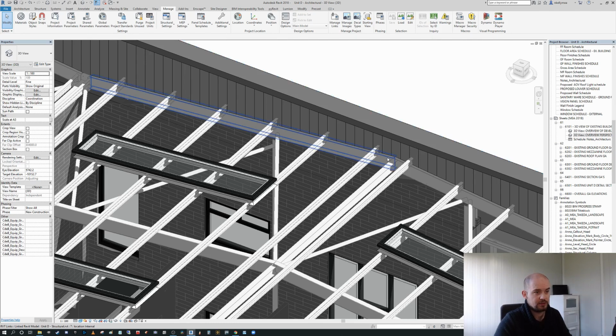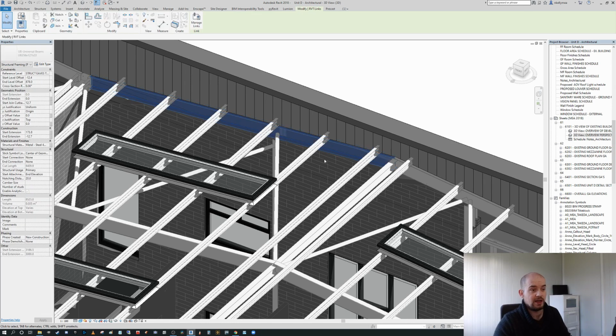But if we tab again, we can actually cycle through the selection objects from where our cursor is, and it will at a point recognize that you're trying to select that individual element from the link, and then you can click and select it. So you'll see here on the properties tab, it's all grayed out. But that doesn't mean that this information is locked to us.